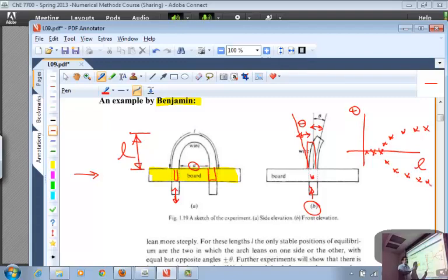So what we say is this is called a pitchfork bifurcation. The solution to the underlying equations. What would be the equations underlying this particular model? They will come from solid mechanics, rigid body mechanics, right? So the solid mechanics equations will allow you to calculate the bending, the deflection, etc. And when you solve that model, you will find this kind of behavior.